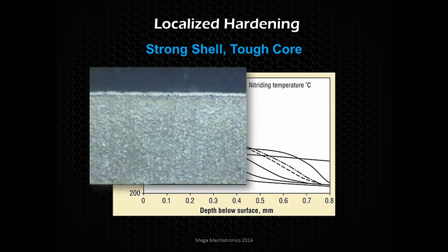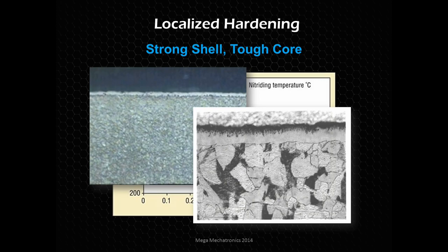And here's a close-up view. You see that white layer is a different crystal structure, so it looks a little different, and as we're getting up a little closer, you see those grains, the light grains and then the dark, and those are different alloying elements and things like that. And then you can see that nitrided layer with again a different structure, and smaller grains, you can't see the grains.